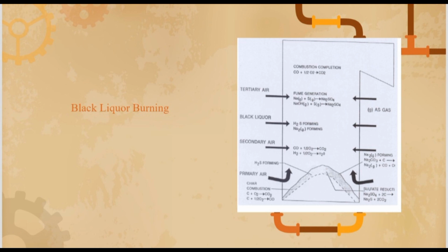Burning of black liquor takes place in the furnace section. The furnace cavity can be considered to be the part of the water-wall enclosure, extending from the hearth to the tip of nose arch. The nose arch acts as a shield for the superheater section and helps tune the furnace gases so they pass through the superheater in a more or less cross-flow pattern.